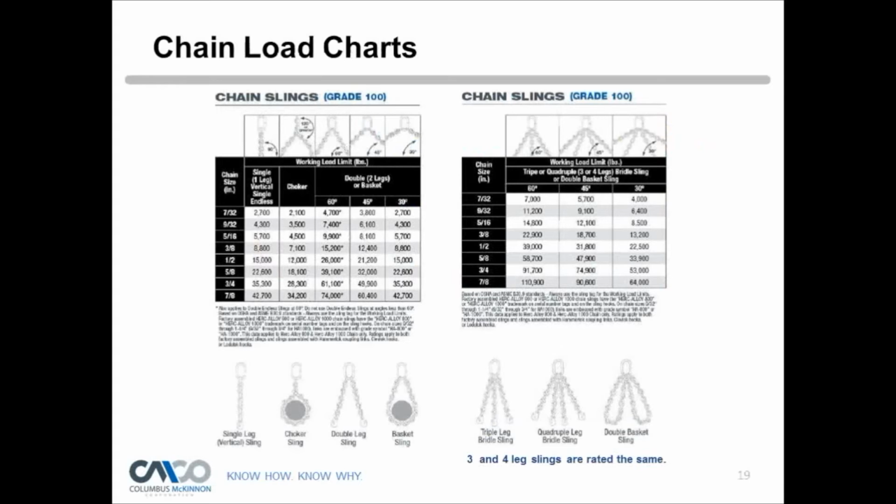All right, so we know our sling reach, but we've got to size that sling for the load, and we'd have to backtrack, depending on how much weight we have. I just used the master link example to give you an example of how we'd have to add additional information into what we found out. But once you figure out what angle it is, if that 60 degrees is going to work for you, then you refer to the chain charts. And here's a sample of our rigging pocket guide that you can get if you give Gisela your address.